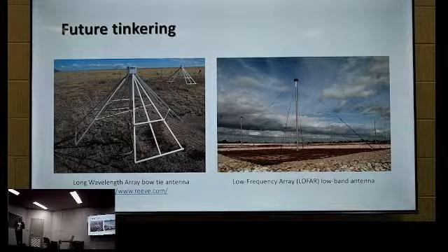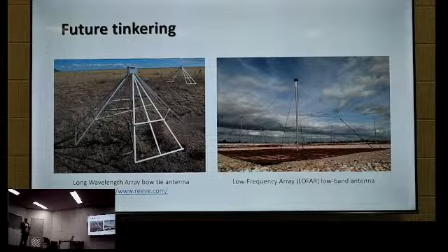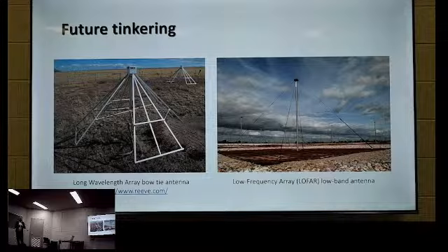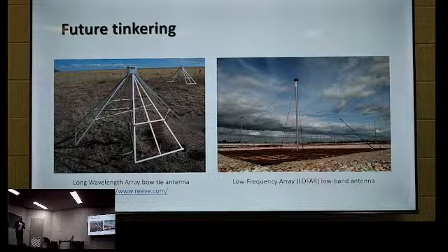Moon bounce: I've got one of the Yagi antennas, the TV type ones, and I've been looking at the moon to pick up a radio transmitter in France. The space debris, and it's debris not as in the cheese, or satellite tracking antenna in Graves in France is, I think, nearly a megawatt, and you can actually see it reflected off the moon in Hobart. The receivers now are really sensitive for all that kind of stuff. That one in Graves is like a radar. Yeah, you're just seeing its pulses, at 143 megahertz, so that's within the amateur radio band.